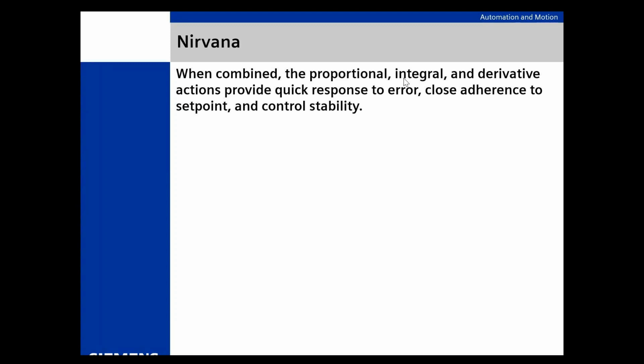It's some fuzzy logic, what people call this. What happens is it goes out and it bumps your process and sees how it acts. Then it bumps it again. It'll bump it numerous times and see how to handle that response. It'll bump it and go, okay, let's say it is a flow loop. It'll bump the process and mess with the valve. Bump the process and mess with the valve and see how everything responds and learn from that.